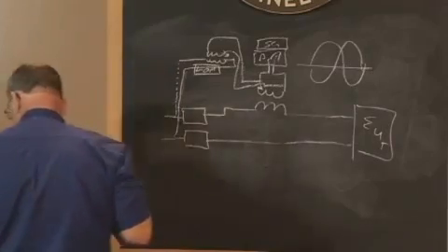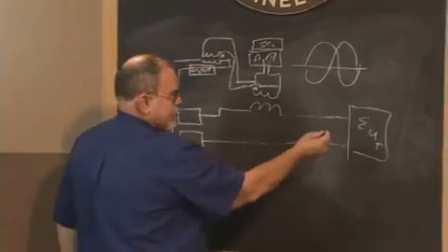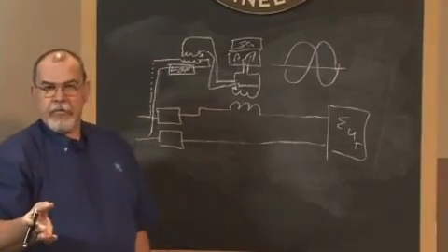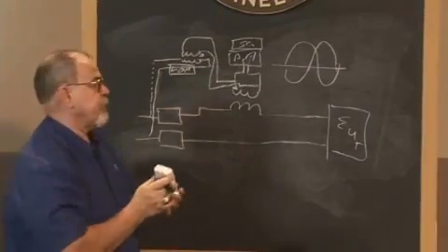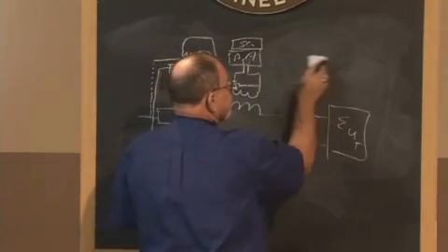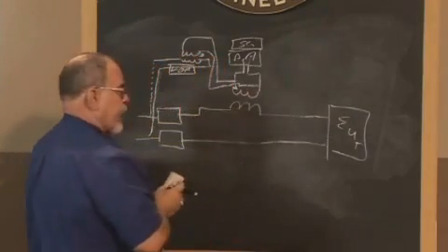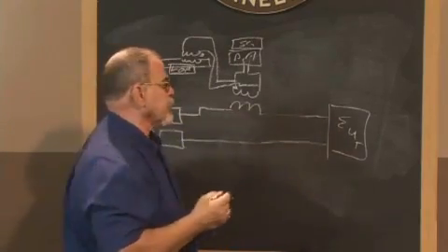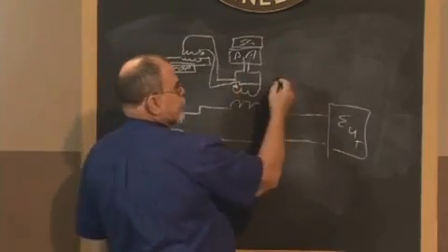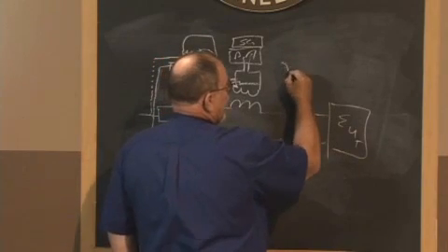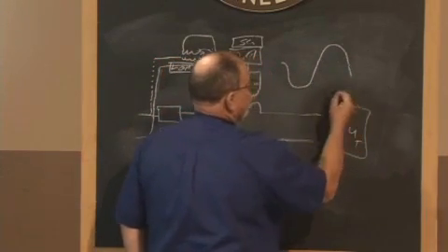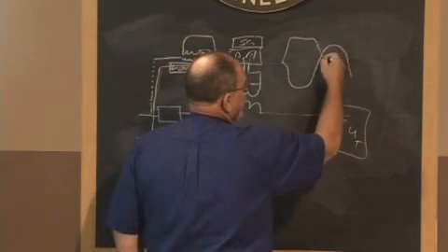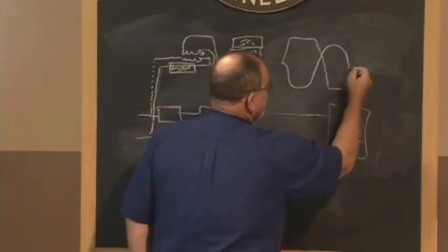The inherent problem is that this assumes that the test article and our load circuit are linear. They don't have distortion. We know that a lot of test articles, switch mode power supplies, things included in the test article present distortion. So if I have a load circuit that's resistive, I have this cancellation waveform of one thing, and I have this waveform for the primary being different.